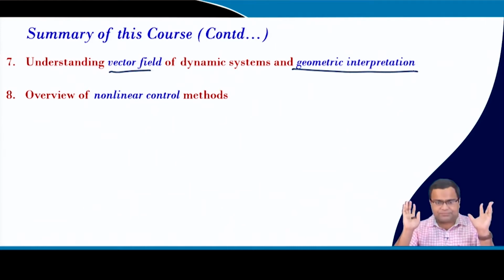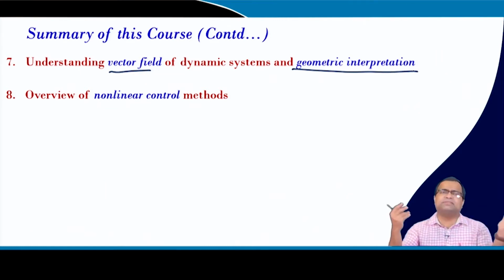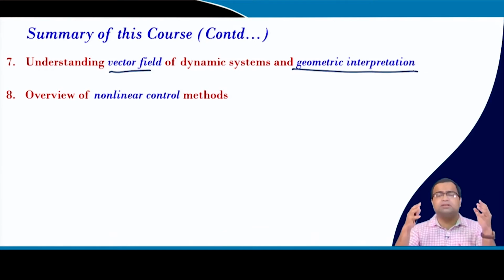because there is a model validity concept. Then we discussed the average nonlinear model, and we have talked about feedback linearization, the exact linearization, as well as the Lyapunov stability based criteria, where we can use the same control but extend the stability range by writing an energy-like function. There we need to prove that the rate of change of energy, where the energy function consists of error voltage and error current, should be negative until all the error becomes 0, and that will ensure asymptotic stability for the large signal average model.